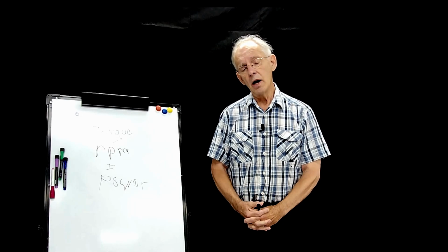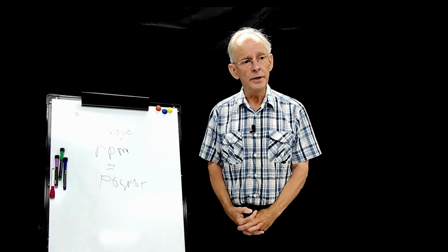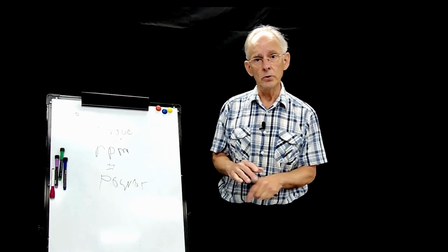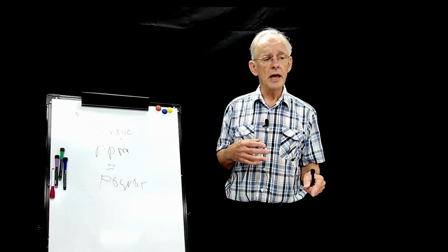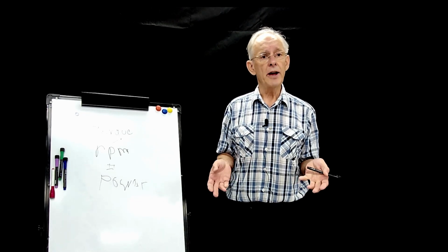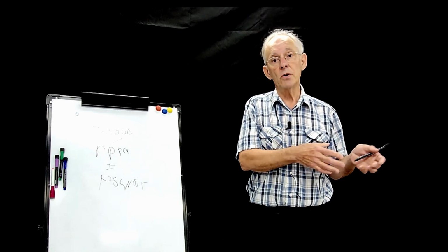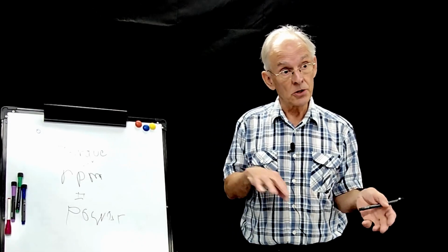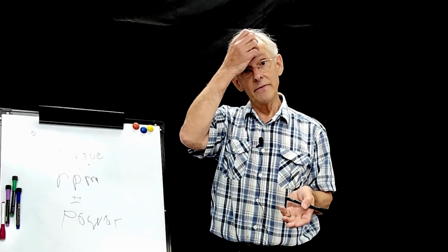If you decrease the speed by a ratio of 10 to 1, the torque also goes up by 10 to 1 on the driven load, which means that you can pull a lot more weight. When you're picking a motor for a conveyor, you're going to back into it. You're going to say, how much force do I need on the rollers pulling the load, divide that by the gear ratio, and that's going to tell you how much torque the motor has to put out.